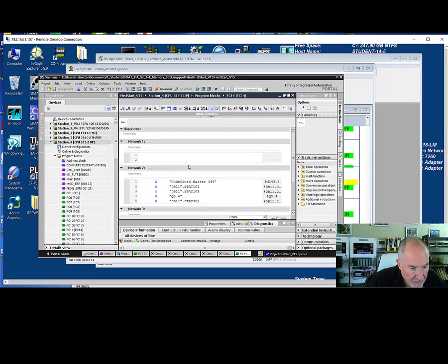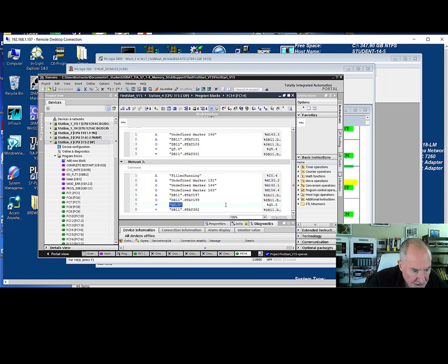I'm going to say here is a coil. This is also in statement list, just like Step 7 was. So Q5.5, what are the things that affect Q5.5? And I have the ability here to once again write down which block I found this in. And in this case, this is FC14, and that's the coil. So I'm going to write down an equal and Q5.5. All of these different addresses could have changed that.